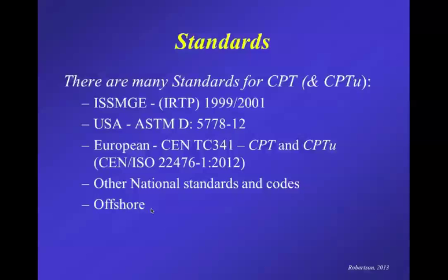That's worth noting, that it may come up later as a question: when you do overwater CPT, everything is referenced to the seafloor, or the bottom of the river or the bottom of the lake. And the reason for that is because the effective stress in the soil is zero at the seafloor, so it's independent of the depth of water. And since soil behavior is controlled by effective stresses and it's zero at the seafloor, then everything is referenced to the seafloor when you do overwater work.